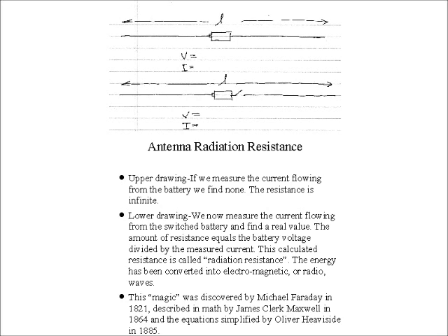And if you take those numbers, if you divide the battery voltage by the measured current, you're going to get a value of 72 ohms resistance. Or actually, in this case, we call it impedance. How can that be? The only thing that changed is the switch. And it's a property of inductance and capacitance, the very things I say constitute this resonant circuit that we talked about.